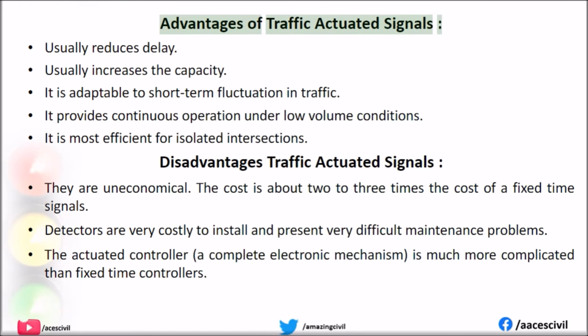Advantages of traffic actuated signals. Usually reduces delay. Usually increases the capacity. It is adaptable to short-term fluctuation in traffic. It provides continuous operation under low-volume conditions. It is most efficient for isolated intersections.